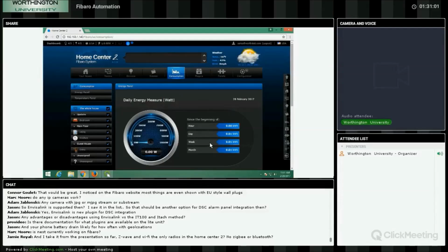There's one device that measures power around here since we see a very low reading. My personal recommendation, and there's a couple ways to do this, you don't have to do any energy monitoring at all. The other option is you can have ZWave devices that have energy monitoring built in. Some wall switches have it, some plugins have it. The last option, which is my preference, is to use a whole house energy meter. It's an Aeon Labs or an AOTech part, pretty inexpensive. It's got the split core clamps on it, so you can actually put it on the main power coming into the main panel on that house or on that electric service. And it's now monitoring the A phase and the B phase all the time and sending that data back.